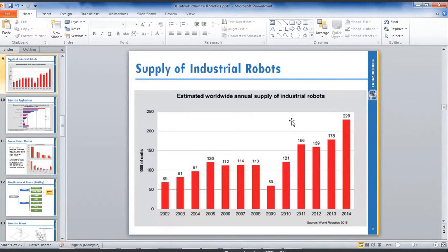The robot has a lot of advantages at that molding station because it doesn't vibrate, it doesn't shake, it doesn't care about the temperature inside the molding, and we can control the speed. If we move very fast, you will have a lot of problems with the LED, because the LED is developed with a semiconductor and a very tiny gold or silver wire.